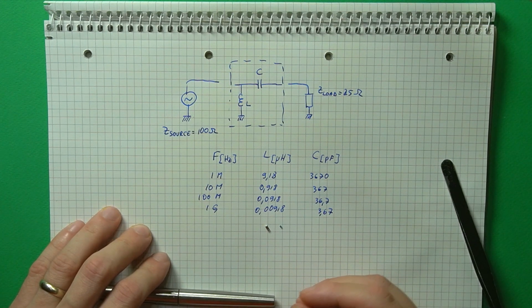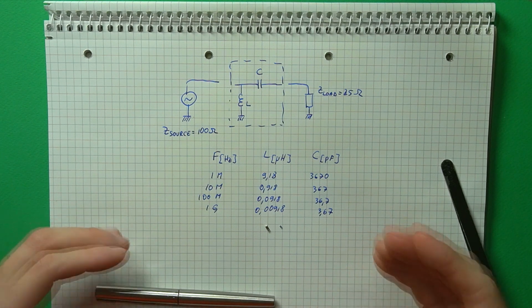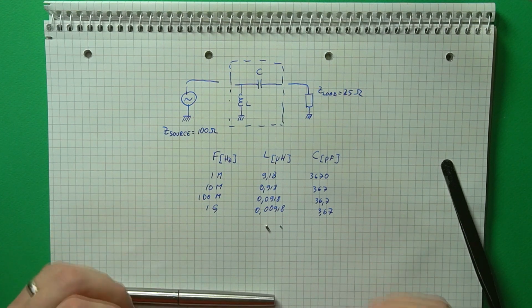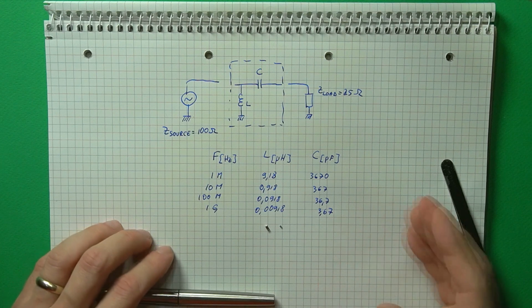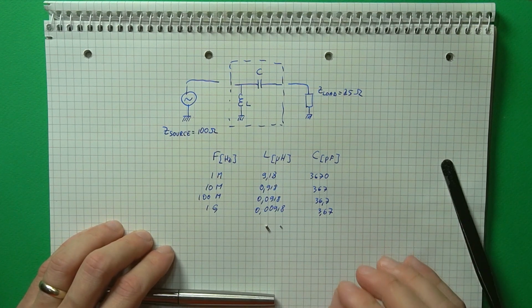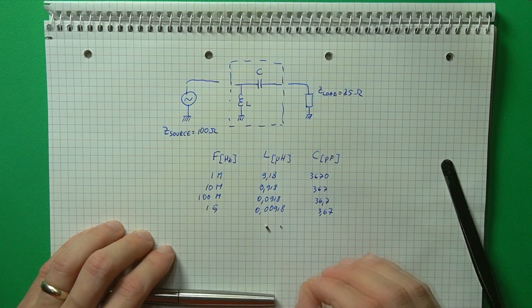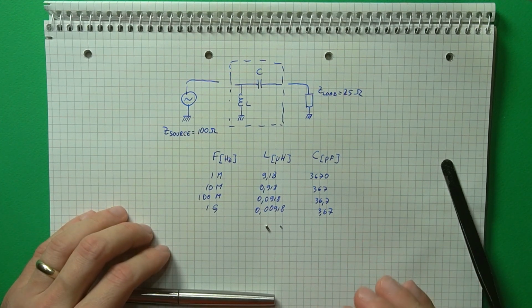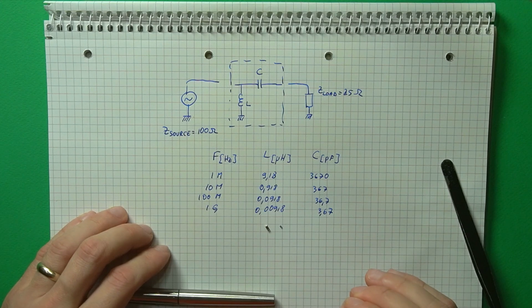So in certain cases, the component parasitics are close to the actual needed values. This of course does not take into account the inductance and capacitance of the PCB traces and the various series resistances. So as frequencies increase, it becomes more and more difficult to design components and interconnections that have negligible effects.